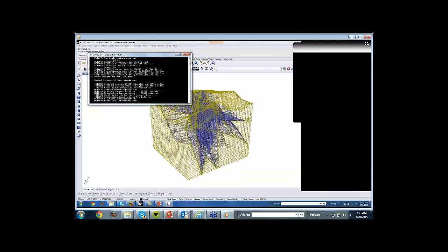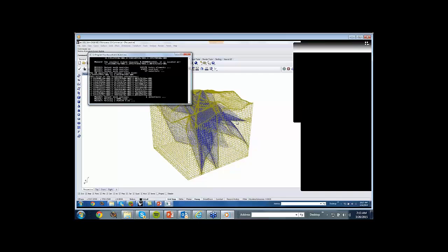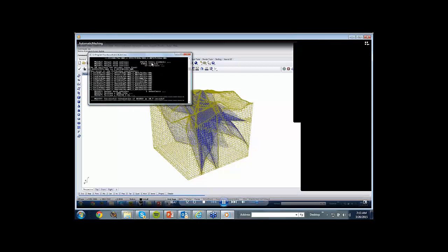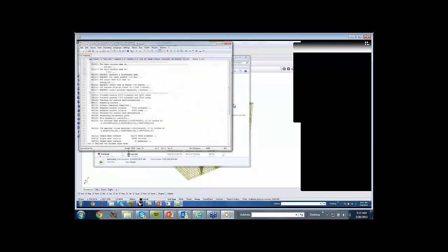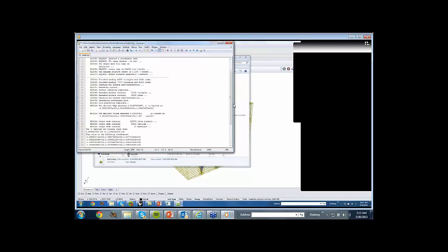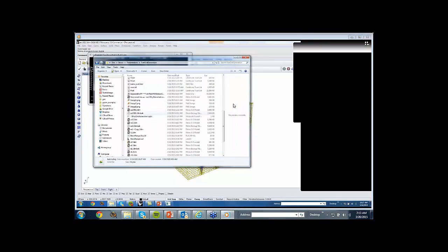The program remeshes these triangular surfaces, which are originally very straight and Cartesian, and turns them into a mesh at the end, which describes how many blocks are in there, and also describes the 10 worst elements of this model. And it produces also a log file that has all this information, so you can grab information from this log file in terms of remembering what's the smallest edge.